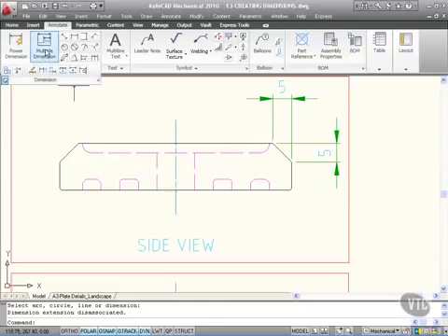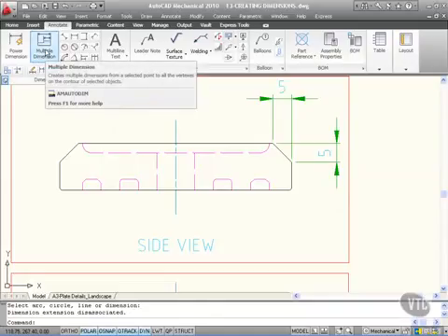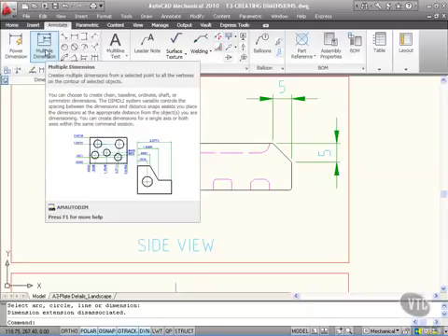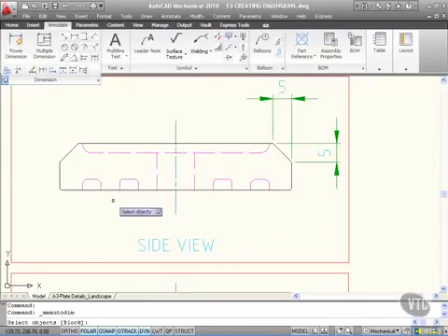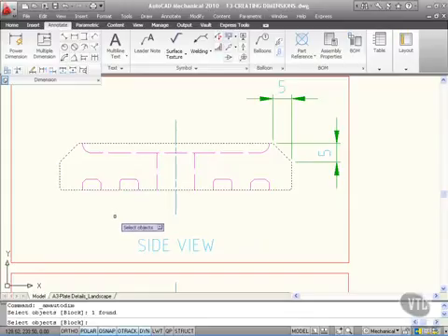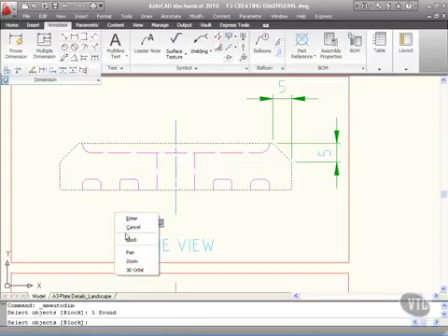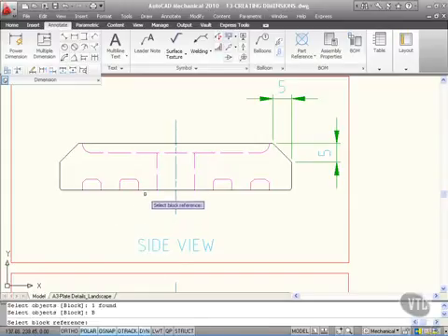Now, multiple dimensions, again, are really cool. So a multiple dimension from a selected point to all the vertexes on the contour of the selected object. Let's check that out. So I want parallel like that. So I OK that like that. Select the object. There like so, right click to confirm and block. Select a block reference. Now I can select a block as well if I want to.